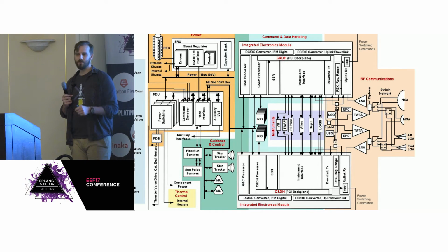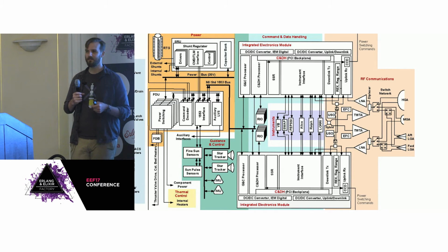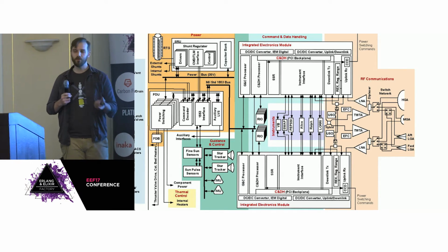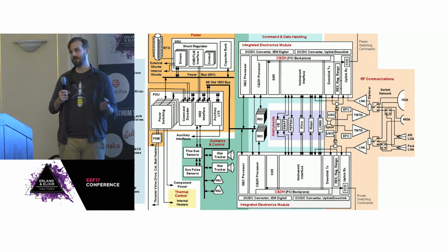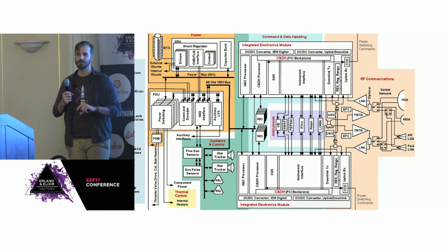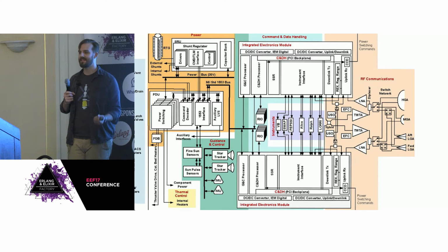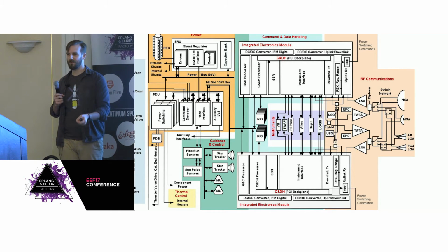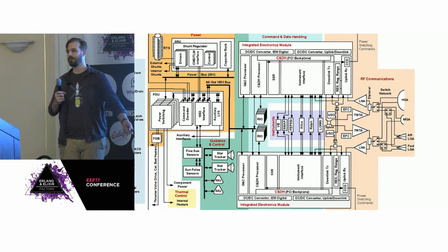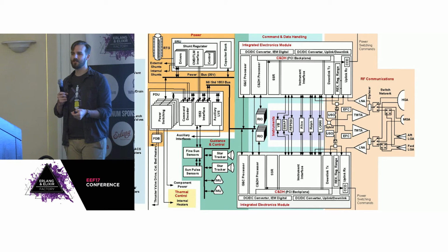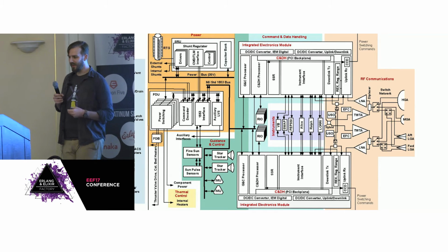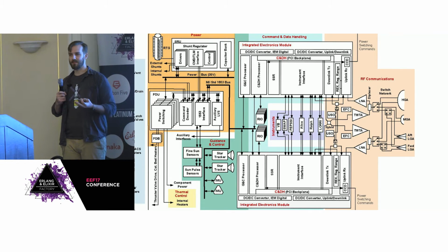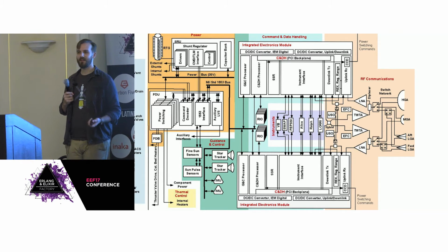It runs a Mongoose processor, which is 12 megahertz, and it has a few hundred kilobytes of available RAM to manipulate. Because the Mongoose processor is relatively tiny. It's worth noting that in any spacecraft, especially a spacecraft that goes out quite far into the solar system, this thing was launched in 2006, which means that it started being designed in 2000-ish. Space people are pretty conservative, so a cutting-edge processor in 2000 wasn't going to be something that they would fly. They would fly something that would be 10, 15 years old. So really, any time that you deal with space equipment, you're looking into the past. My understanding is that Johns Hopkins Applied Physics Laboratory built New Horizons. Now they've upgraded to something that's a couple hundred megahertz processor in any new thing that they fly.